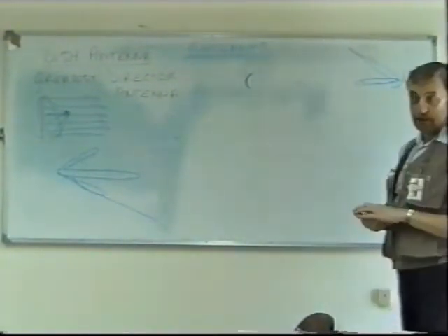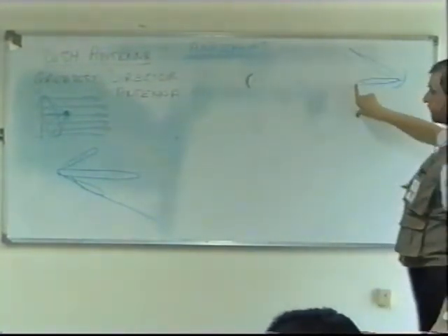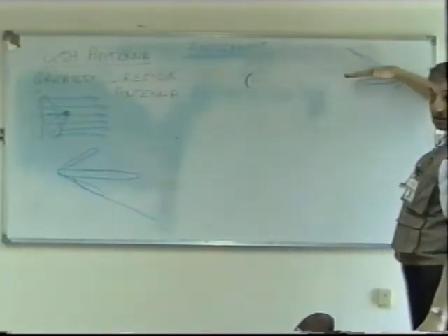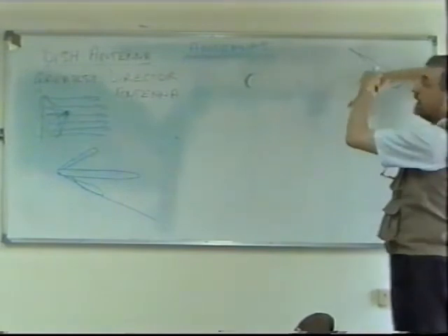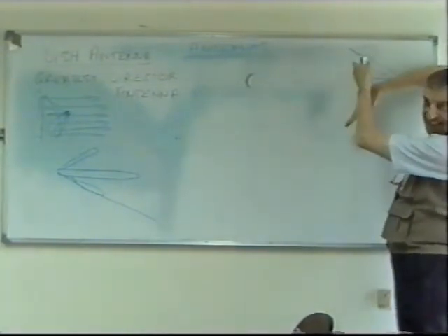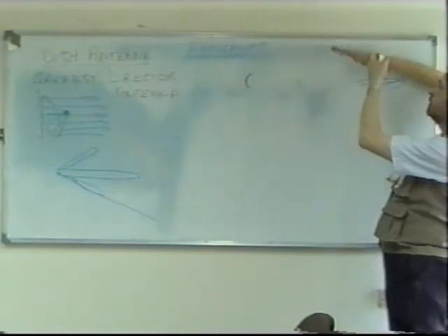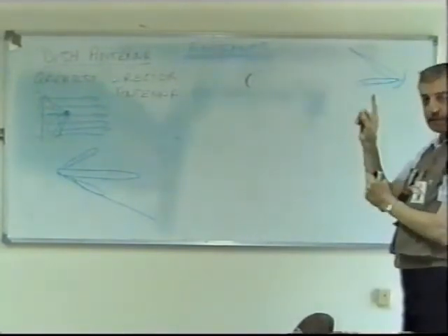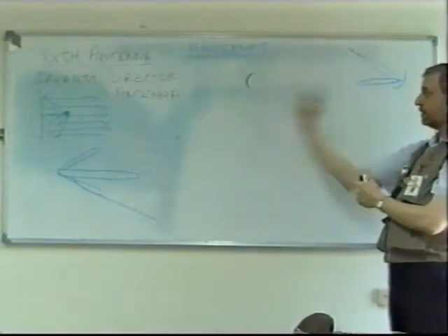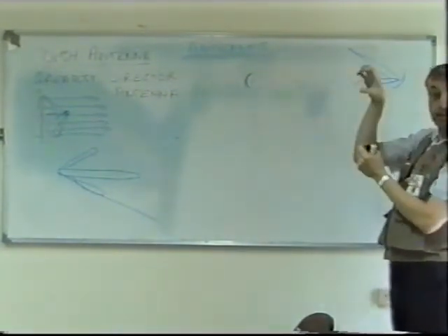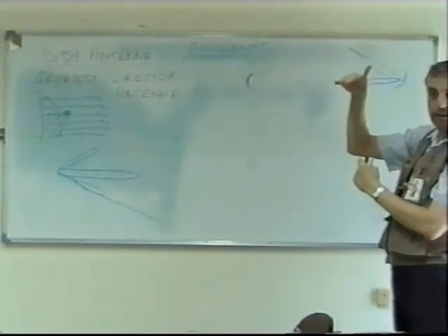And now, what you actually have to do to align the dish is move your dish so that you get a certain signal here, then you should get a bigger signal as this one comes into play, and then an even bigger signal, and then a smaller signal again on the next lobe. Do you see? So the idea is to move the dish, look very carefully at the signal strength, because you're receiving a signal from the other side. So you look very carefully and find out which is the biggest signal, the highest signal that you get.